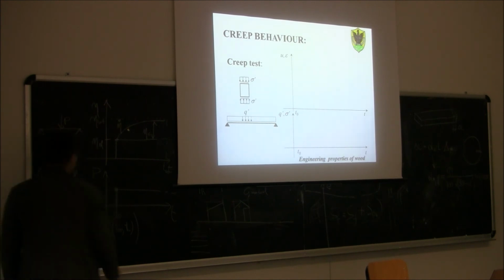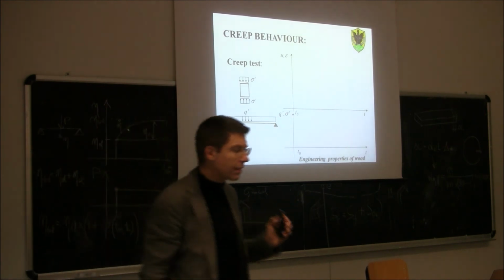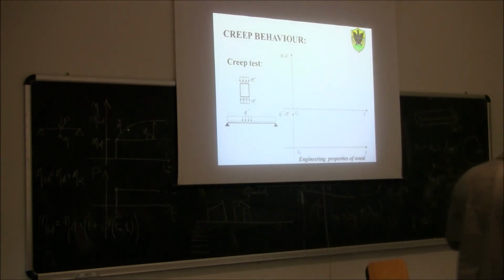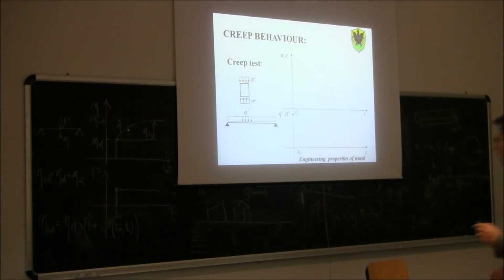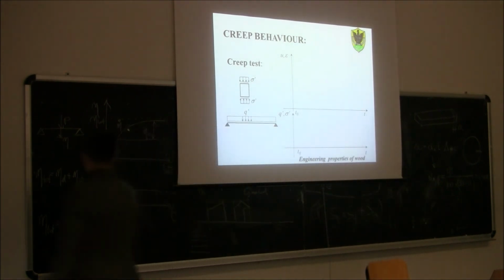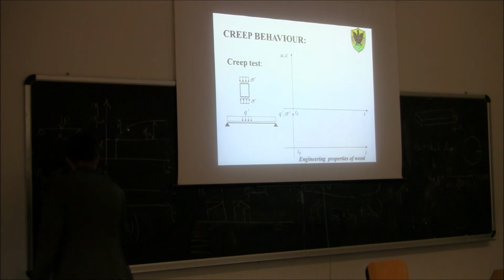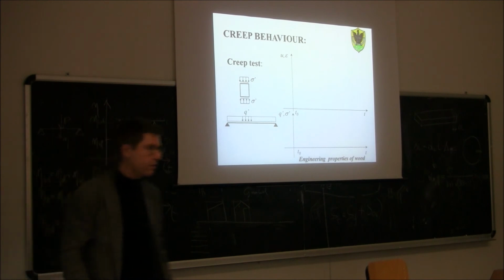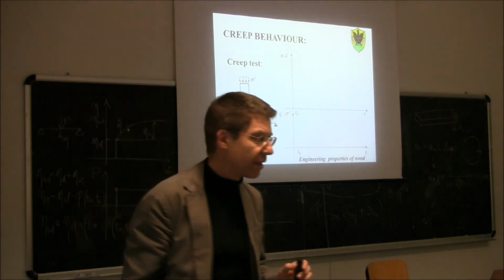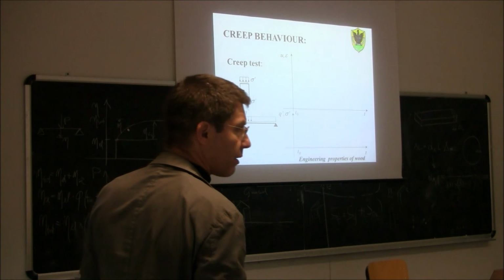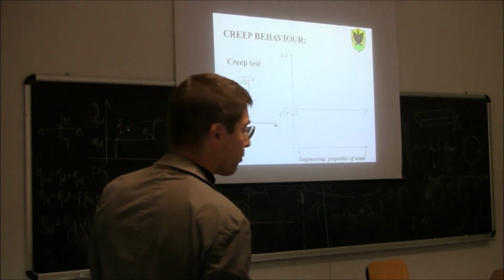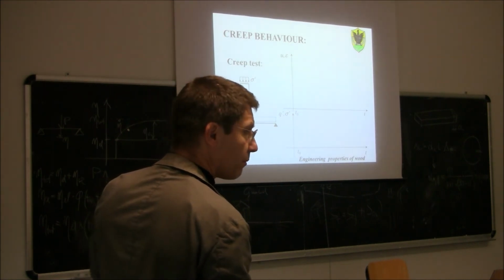But if we assume that our material is a viscoelastic material, then the eta creep can be calculated by multiplying the eta elastic times phi of T infinite, T0, where phi is called creep coefficient. So if we have a viscoelastic material, we can use this formulation here, which of course then leads to the formulation that your colleague said before.